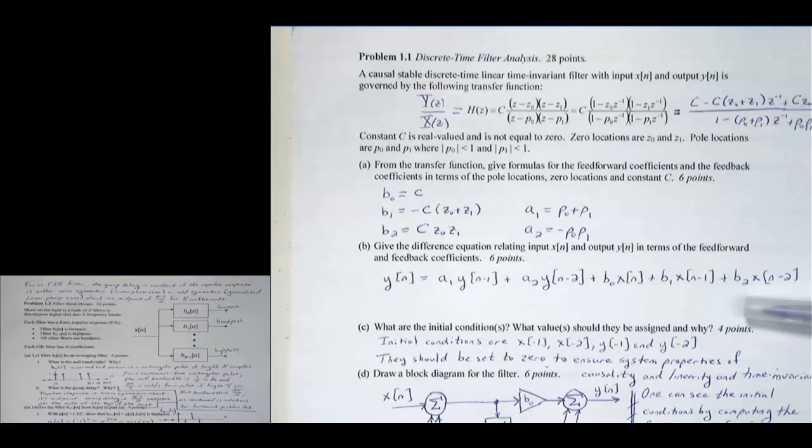All right, so I have a number of channels. And we talked about decomposing things into 2 channels when I did Lecture 5, Part 1. We talked about a 2-tap averaging filter and a 2-tap difference to divide the input signal into low-pass and high-pass channels. This is a generalization of that discussion into n different filters, as we had in the lecture.